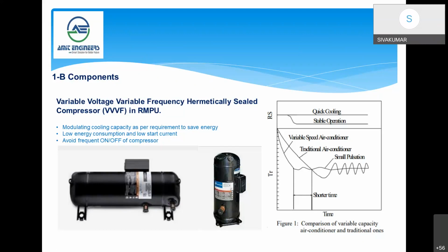Yes, sir. Proportionally, it has to be reduced. Theoretically, there is a formula. If we reduce only the voltage and not the frequency, the motor current will not be balanced. So that's why the motor will get heated up.